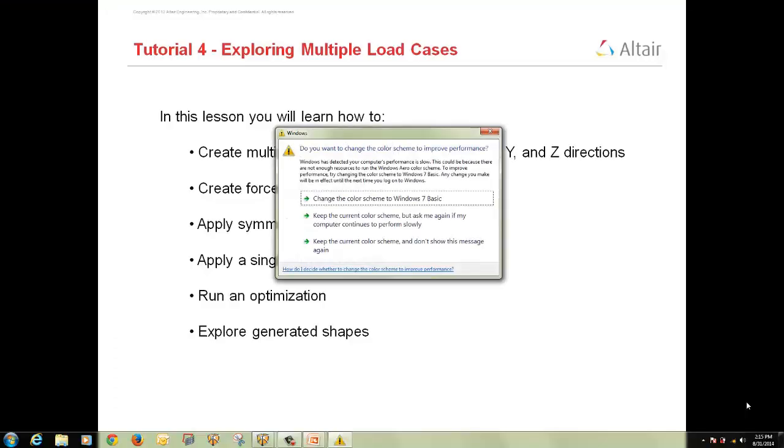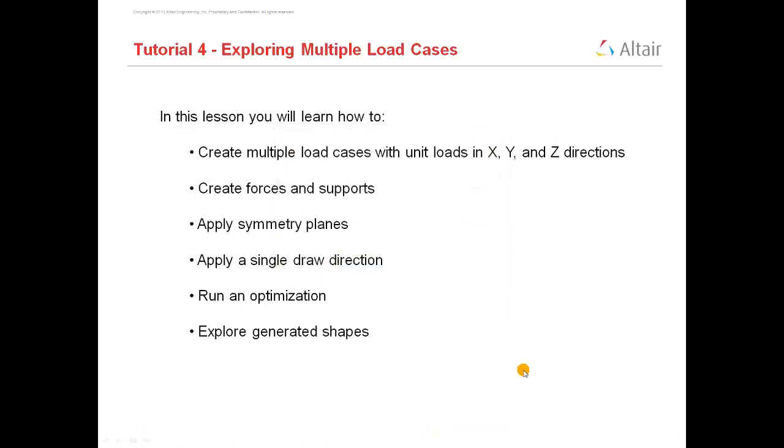So let's start with today's session. In today's session, I am going to discuss tutorial 4, exploring multiple load cases. In this lesson, we are going to see how to create multiple load cases with unit load in XYZ direction, then create forces and supports, apply symmetric planes, and apply a split draw direction, not a single draw direction. Then run an optimization and explore the generated shapes.